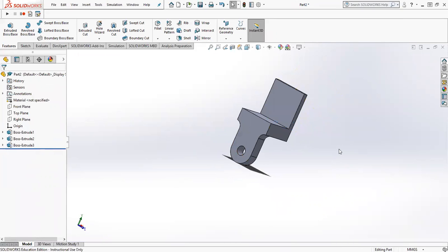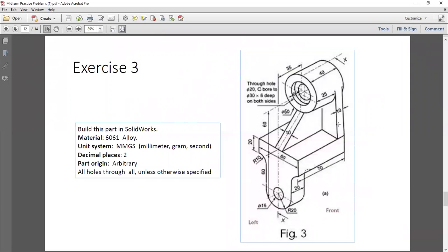And then we are going to, let me pull up the drawing. All right, so we just drew this object here, and now we're going to draw this portion. We can see that it starts 35 millimeters from, if you go down, it starts 35 millimeters from this surface. So we're going to create a plane that is offset from this surface by 35 millimeters. So our plane will end up right here. And then we can draw these circles and perform extrudes and cuts.